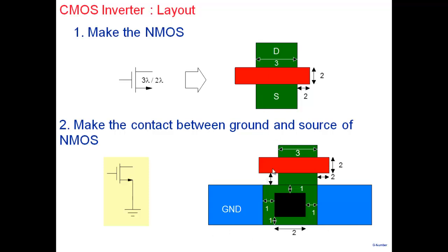And this N, that region that you saw here, I extended it over here. This entire region, I made it N. Now note that this entire region is N. And on top of the N, the metal is running. Please keep in mind, on top of the N, the metal is running. Why? On top of the N, what is actually there? Silicon dioxide.